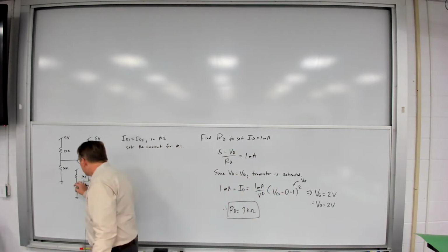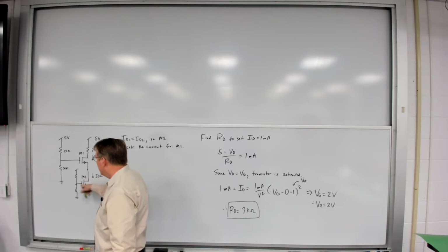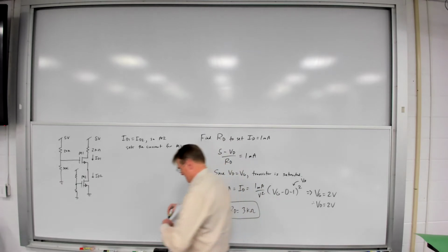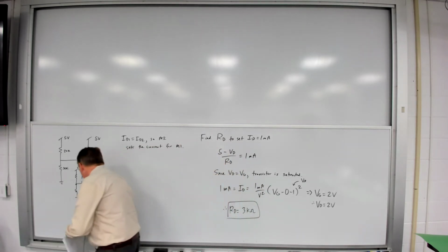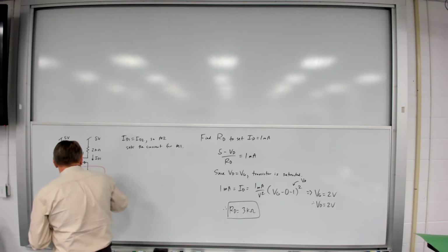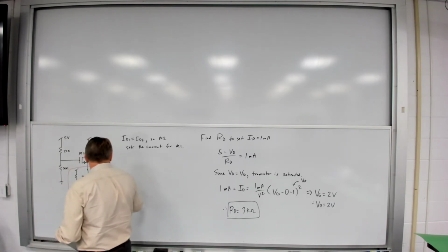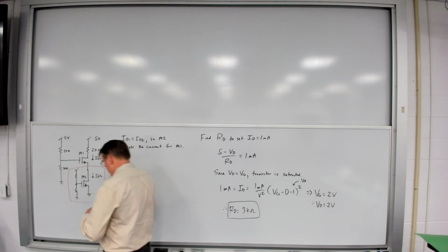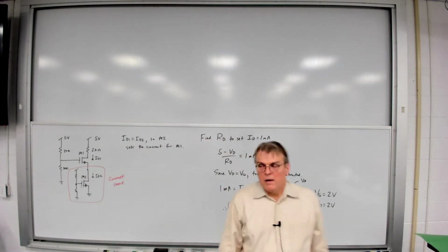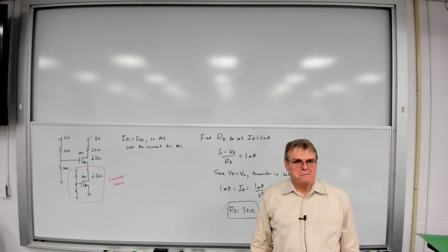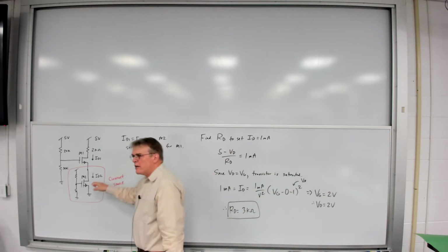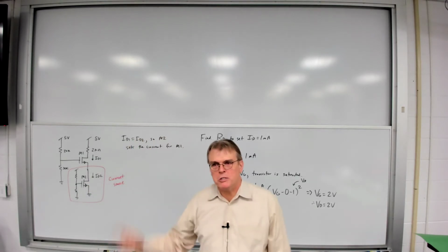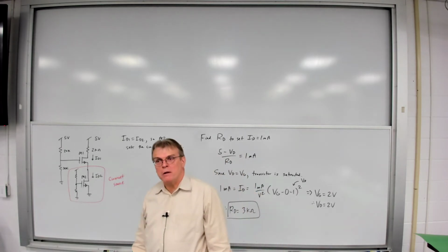I'm doing nothing except just taking a standard transistor and then adding its own resistors here in order to create this current source effect. So this portion here becomes my current source. Turns out that works incredibly well. In this case, the drain current is as stable as we can make it by using M2. So the more stable we can make that, then the more stable the M1 current is going to be.